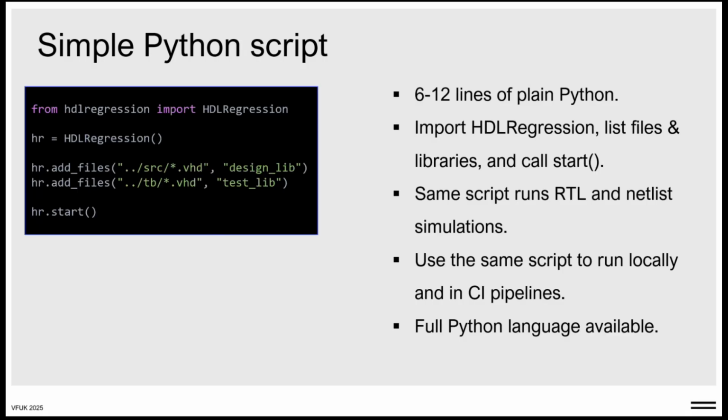And as you can see here, there are not many lines of code needed, and the same script can be used for running RTL and gate level simulations. And the same script is also used for running locally on a computer and on a continuous integration server, which is great for local debugging and testing. And because we are writing in Python, we have the full Python language available to configure our tests.